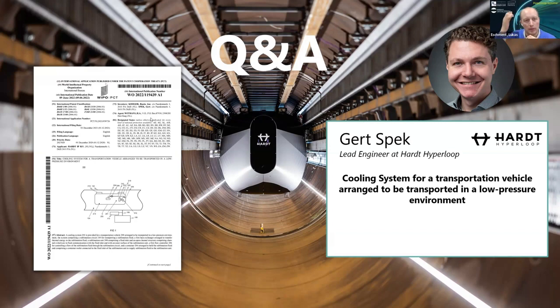And that is already including the doubling because of the defrosting and frosting? So I took now for the cooling of the condensers just the cooling, keeping the coolant. If you defrost, you can probably use the atmosphere to your advantage by either running a much more efficient higher temperature coolant flow through there, or other ways to defrost it by exposing it back to the ambient air and draining it as a liquid. But it's not included in this figure now.